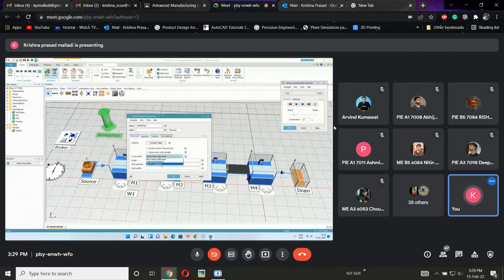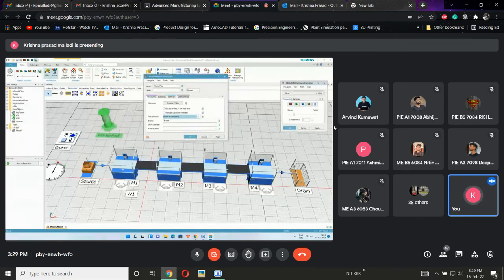The third option is beam to workplace. In beam to workplace, when the workpiece enters the machine, instantly the human also appears at that machine. That is beam to workplace, which is not that useful in plant simulation. Generally in plant simulation, any industry or project is done on these two bases only: first, move freely within work area, second, walk along footpaths. By considering these two, they calculate how much time it takes for humans to reach the workplace, and how much time it takes to reach from one area to another. All those things can be calculated in these two only.